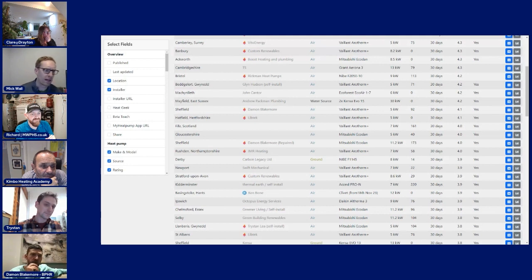Yeah, we put some IMI valves on every radiator, and we found they were restricting flow and they weren't very good, and we swapped them out, and performance improved straight away. So you can see where you make your mistakes, and you can rectify it, and you can improve. I've made massive improvements in my hot water performance because I can see that.